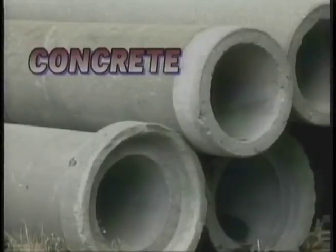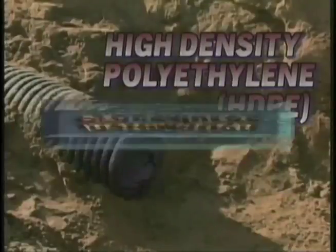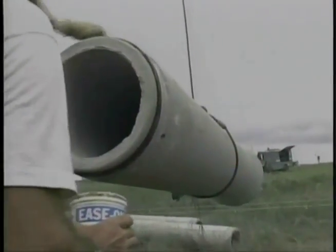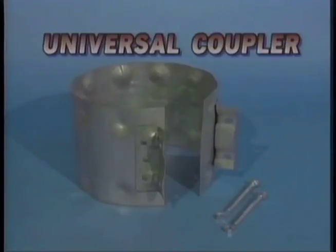The most common types of pipe used for storm sewer installation include concrete, corrugated metal, and high-density polyethylene. Area practice and project specifications will dictate the type of pipe to be installed. Concrete pipe may use bell and spigot joints similar to sanitary sewer, but corrugated metal pipe and high-density polyethylene are connected with manufactured couplers. A universal coupler is one type of connection used to join corrugated metal pipe.